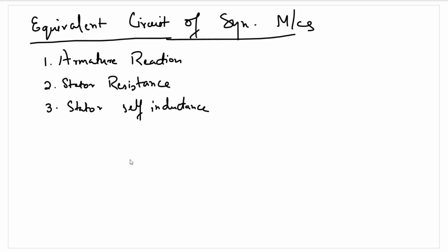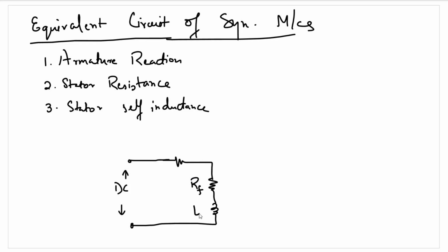So, the rotor circuit is pretty simple since we know that a DC voltage is applied to the rotor windings. The rotor side will actually include the rotor resistance and the rotor's inductance. So this is the rotor side, that's also the field in this case, its inductance and its resistance. And we can also have some external resistance that can be used for field current control in case of the DC windings. So this part represents the rotor windings of the